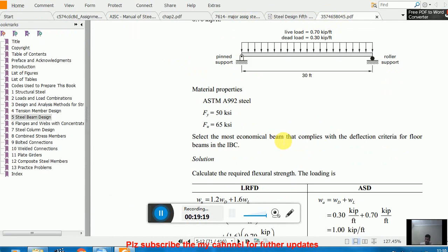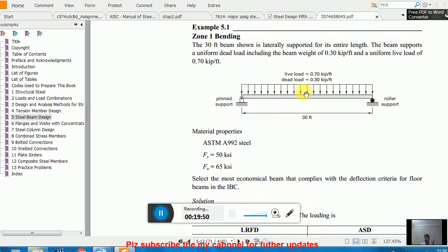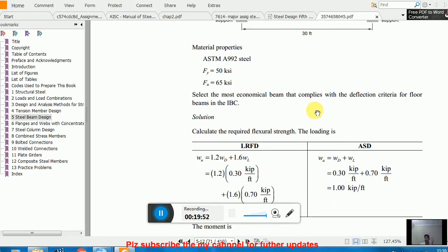Deflection is very predominant in designing such steel beams, because sometimes the plastic moment is developed and your section is able to take the acting load, but once you design the section, although it is perfect and can take the acting load and moment, it fails in deflection, with excessive deflection. That's why we check the section for deflection as well.